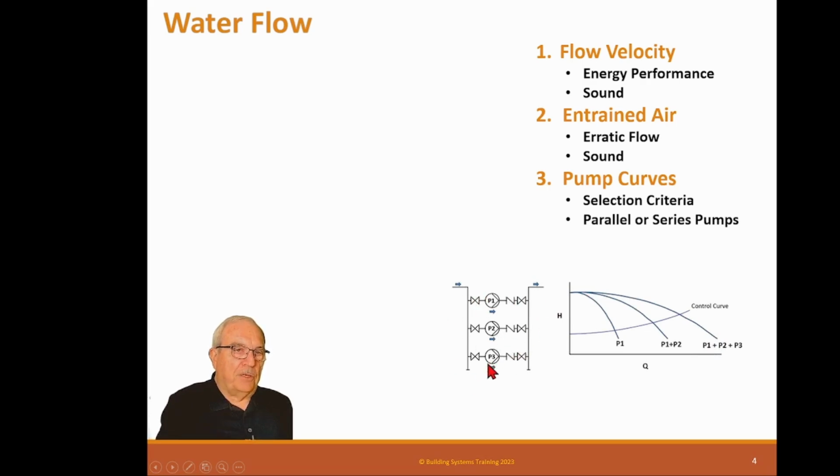So the standard within the industry is, if you just have 2 pumps, you don't have a third one, then we assume that 1 is the load and 2 is a standby, 100% standby. Maybe a bad assumption. So you may have to actually add up all the loads to see what the deal is. If the loads are twice this pump, then it takes 2 pumps to run for the load, and the third one is standby. You should never have something that runs 3 pumps together, but you don't know. So whatever the design is.